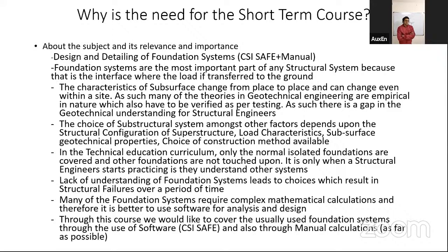Even if you look at a normal geotechnical report, not many of us are able to interpret all the results correctly, or they are not able to interpret what is being said in the geotechnical report. So there is a gap between geotechnical understanding and structural engineers. Most of the time, you just say that yes, there would be SBC of 15 ton per square meter, isn't it? You must have heard people saying that this SBC would be 18, this would be 15, this would be 20, but generally we don't have much sense of it at a larger level. So it is only experience based.